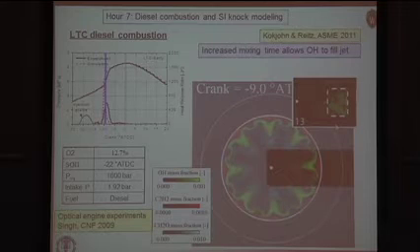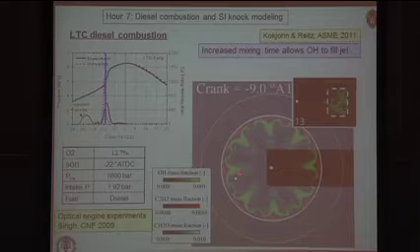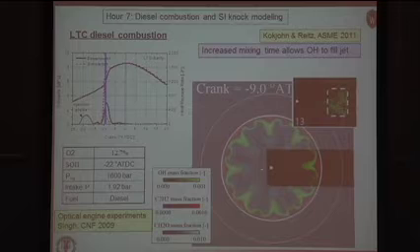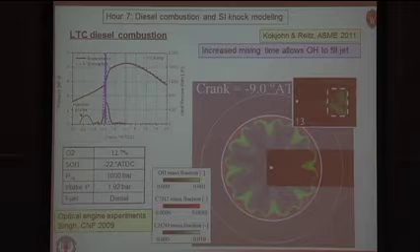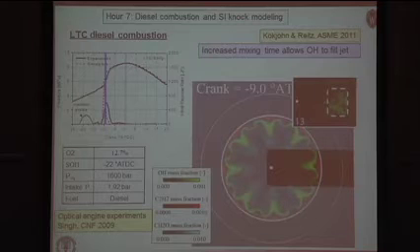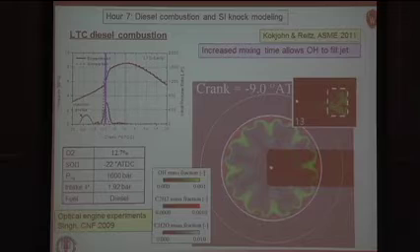If we continue then in time, we see now the onset of second stage combustion. That's indicated by the appearance of OH, all this green stuff that you see here that came from the low temperature regions where the formaldehyde was located. And of course, these jets are all now striking the bowl wall. And in that region, we see this red stuff, which is the soot precursor, the acetylene being produced. And if you've got a good memory and think back to that PCCI picture I showed you before, you saw all of the luminosity was around the edge of the bowl for this PCCI, or low temperature combustion. So very consistent with what we're seeing in this picture here.